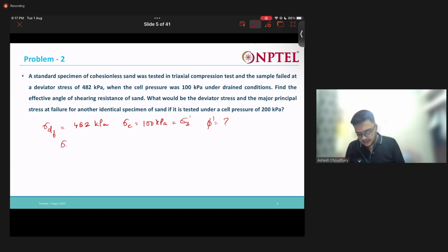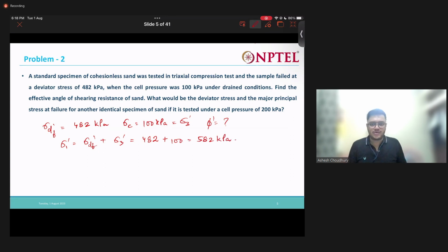Now what is my major principal stress? It is nothing but deviator stress plus sigma 3. It's nothing but 482 plus 100, 582 kPa.